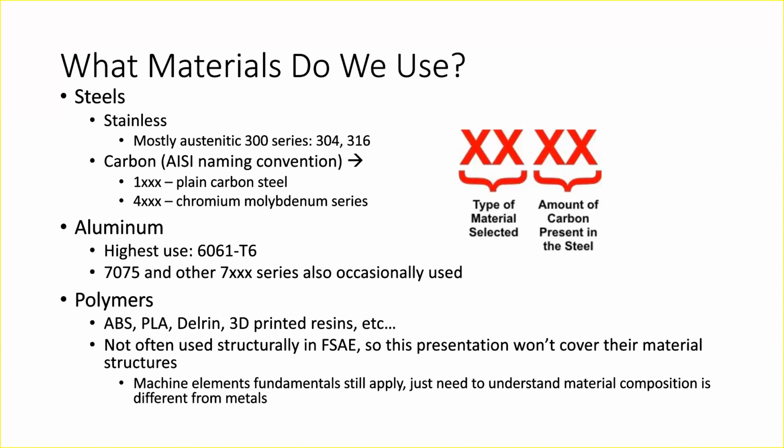You select a material, you go to the design review, and some more experienced members will point out, hey, this part isn't hard enough in this region, or you might want to heat treat it. And you learn from experience, and you learn to recognize when you might want a certain type of material. And there are also very common alloys that you'll tend to choose.